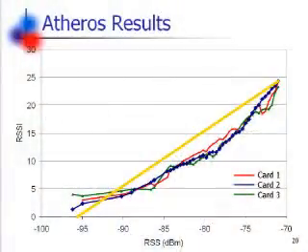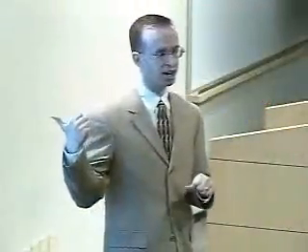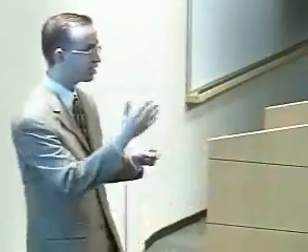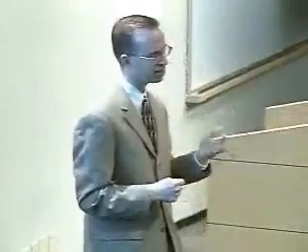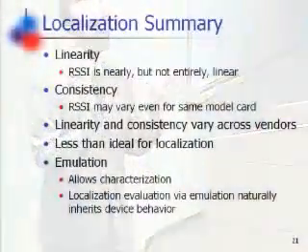The next chart, let me show the Atheros results, and that'll probably get at the question to some degree. So these cards have apparently been calibrated because between 2 different Atheros cards, we get very, very similar results. You see that there is a little error there, and some of that is probably due to the emulator itself. But you see roughly a dB-ish. There is a calibration question across different paths, and right now we're at about, I think, 2.5, maybe 2 dB of maximum error between cards. So I can talk more about the calibration offline. Calibration is a pain in the neck.